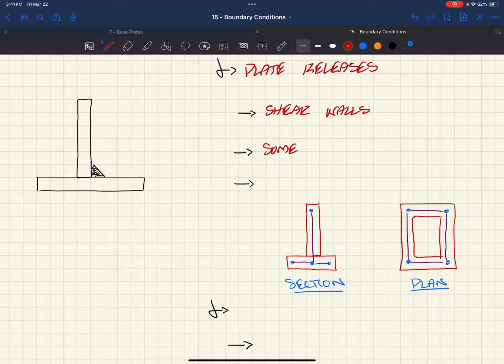As I mentioned, we use them in some plate connections. For everyone in steel, except for Jocelyn, but even with steel 1, we talked about connections with two plates with a fillet weld. This could be a shear tab attached to some column face. And we talked about the reasons for wanting to weld on both sides. So typically we'd want to put a weld on both sides.